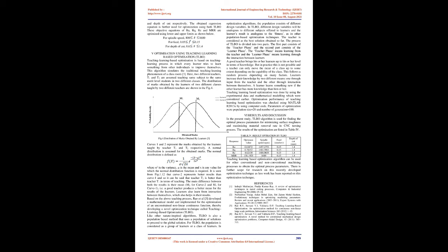In this study, spindle speed, S, feed, F, and depth of cut, D, have been considered as process variables. The working ranges of these parameters were selected for subsequent design of experiment using response surface methodology. The process variables with their units are listed in Table 2.